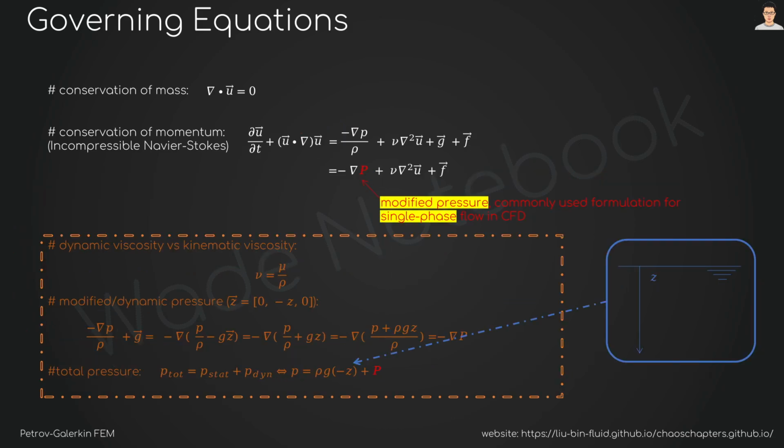Before discussing the finite element formulation, we assume that the fluid density is constant and divide every term in the Navier-Stokes equation by the fluid density. In other words, you may imagine that we take the fluid density as unity. This is very helpful for numerical stability in scientific computation. Let us explain this further.